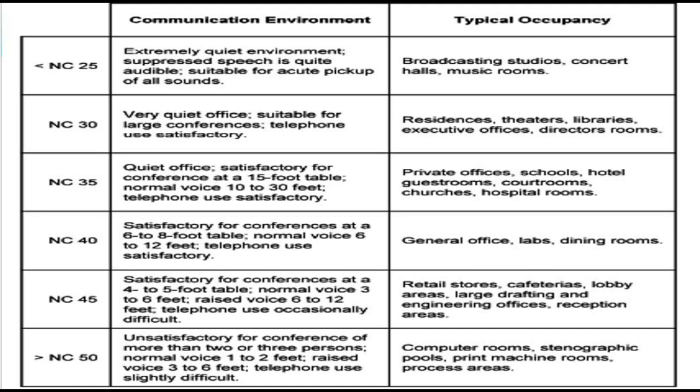If you are trying to keep the room quieter, we should select the lowest noise criteria, 15 or 20. Another factor which can cause the NC level to go up is an increase in face velocity, and it can also create more pressure resistance against the blower's delivery of air volume and increase the noise.